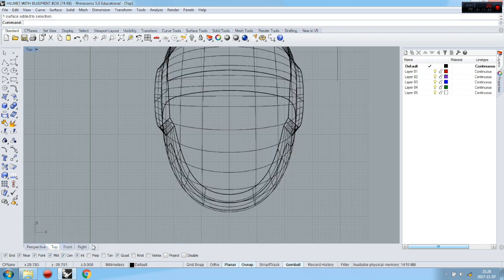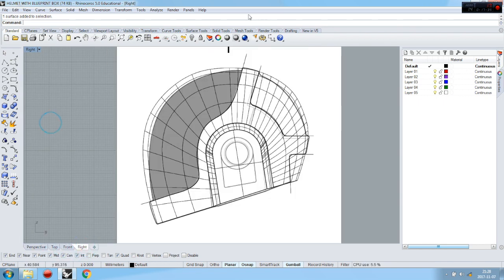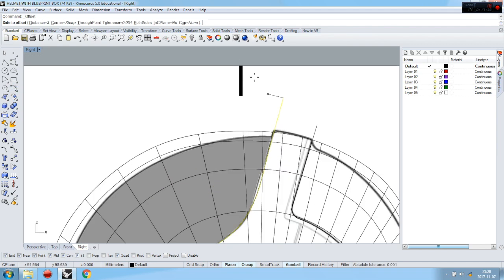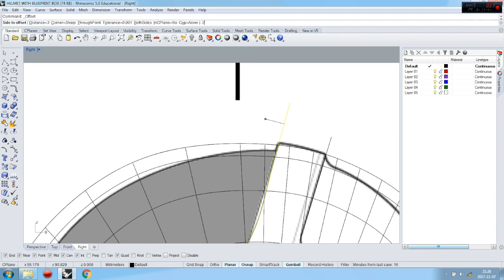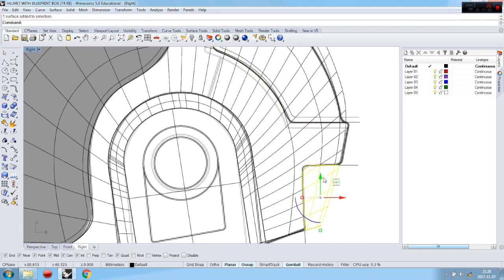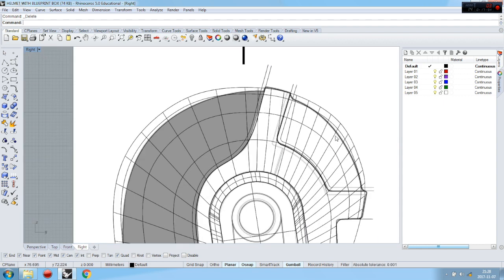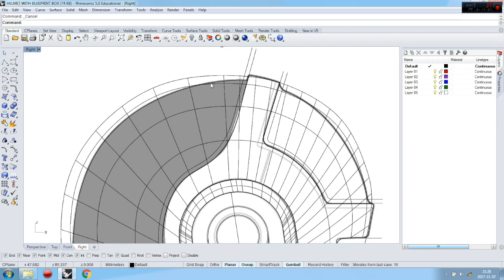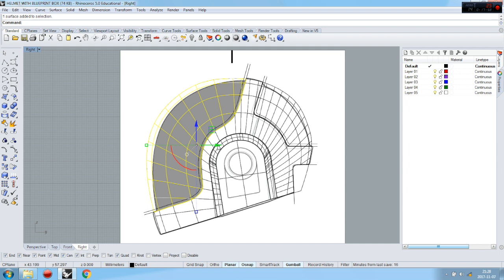So I need to get that curve and make an offset. It's going to be 2 here, maybe 2 is too much, 1 is enough, and the same here. I don't need that bit actually, so I can delete it, and I need to just move it. If you click on the arrow and type, for example, 3, then you're moving them. 2 is a little bit too much.